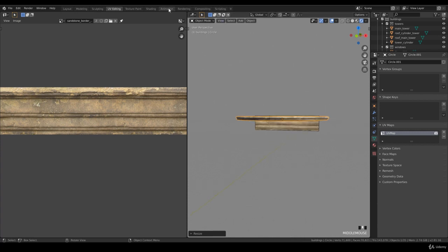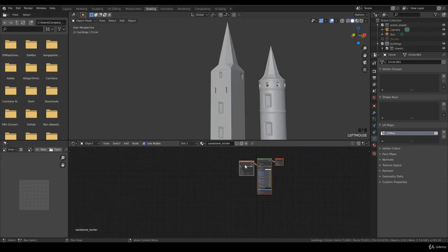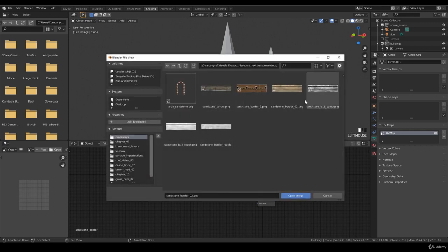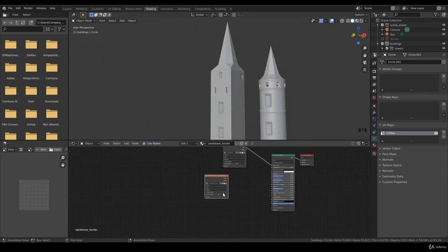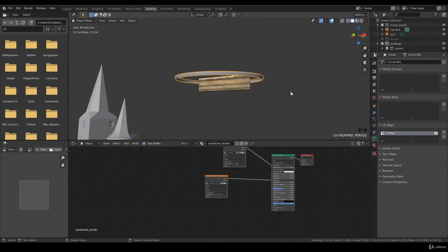Alright, so now I want to do some shading on it, just a roughness and a bump, because I do not have a normal map image. And that is the roughness, because I have two of them. And we have to select the border too, otherwise it looks weird. Non-color, I put the color in the roughness, and I want to have a specularity of 0.02. Of course I want to highlight this.